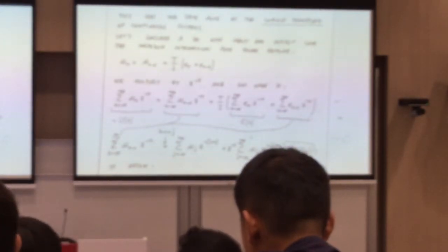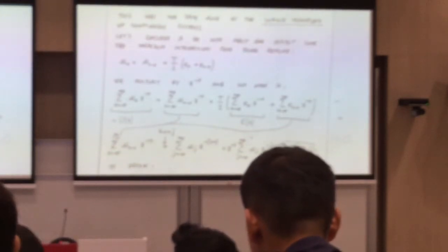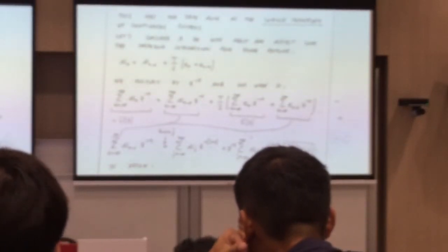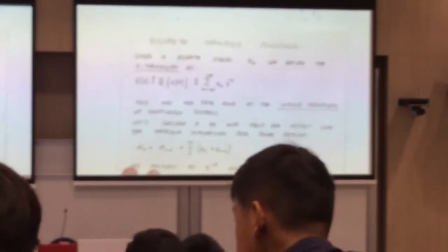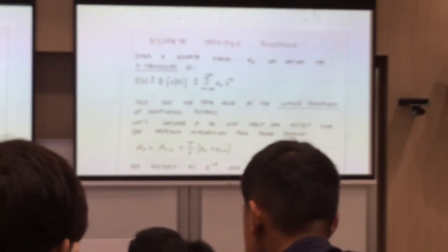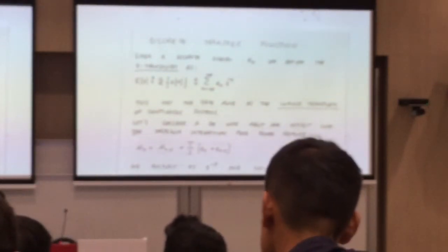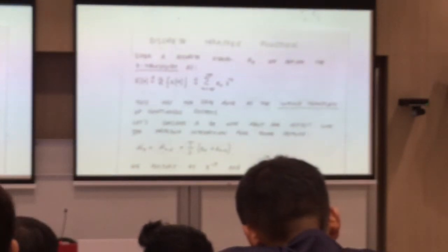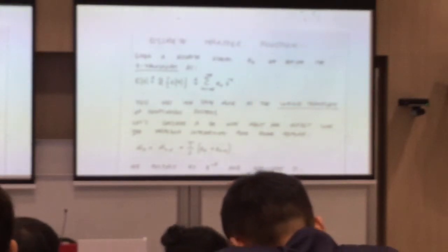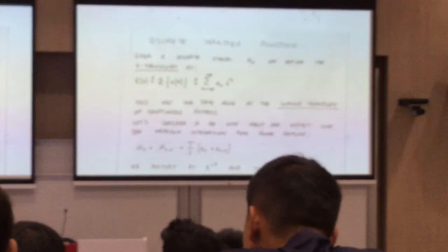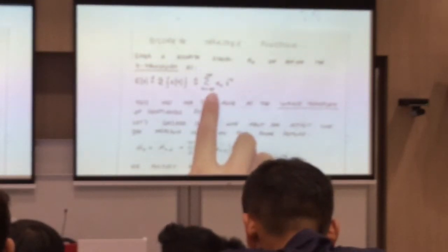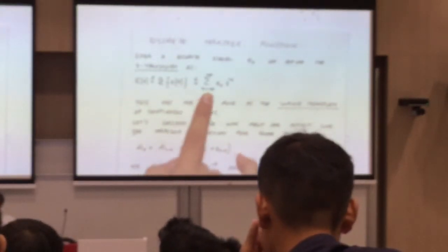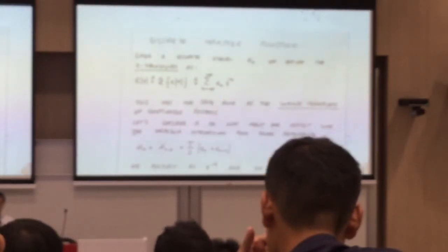In the continuous domain, you have the Laplace transform. So eventually you get your S function as a transfer function. So similarly, in digital control, we have the Z transform. Okay? The Z transform compared with the Laplace transform, they are very similar. For the Laplace transform, you need the integration of your function multiplied with e to the power minus st, with t from negative infinity to positive infinity, right? But here it is the same thing. But instead of integration, because in digital control we have no integration, we do summation. So you have this sigma. Sigma means summation. And you multiply with z to the power minus k, right?